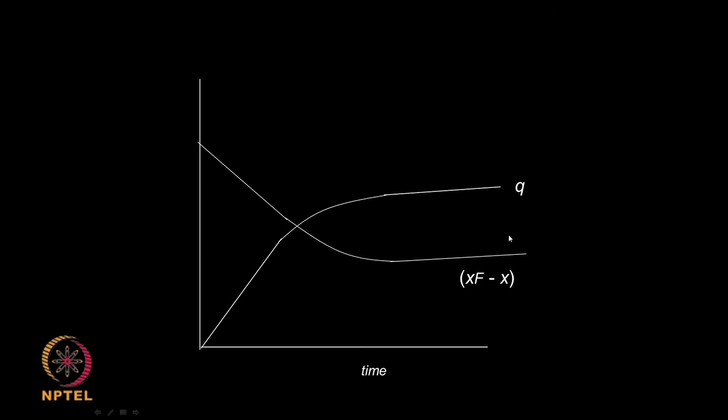After this, there is no adsorption that is going to take place. So, I need to stop my adsorption process and replace the adsorbent with fresh adsorbent, otherwise it is of no use. Generally, by this time the adsorption process is stopped and then they either reactivate the adsorbent or charge it with fresh adsorbent. That is what is done.